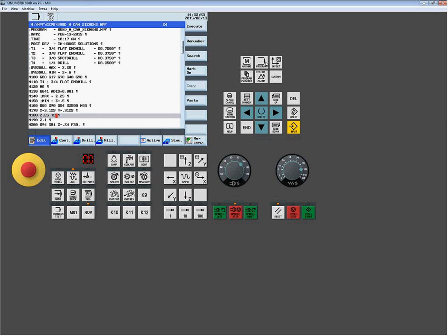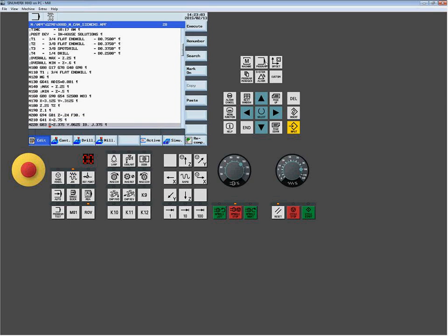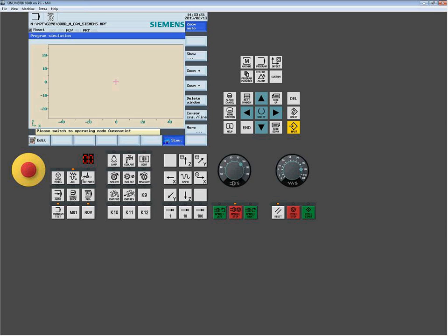So we're going to run this program, and then we're going to try a couple of things, and we're going to notice that nothing's changing. And then I'm going to show you what's happening here. But these are the things you're going to start to have to deal with when you're dealing with post processors, especially debugging them. A lot of times it's designed for one machine or one control. You're trying to apply it to a little different machine that was set up differently, and you make two very different results. Okay, so if we go to simulate and run this part,